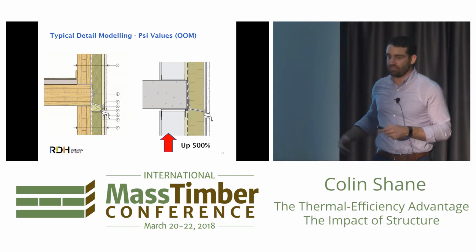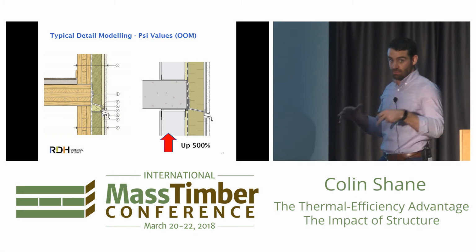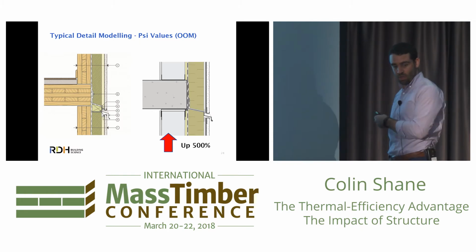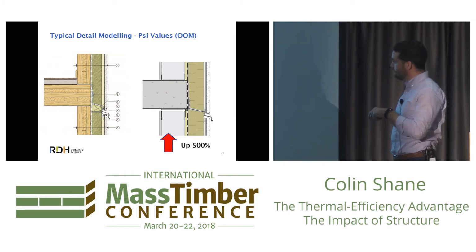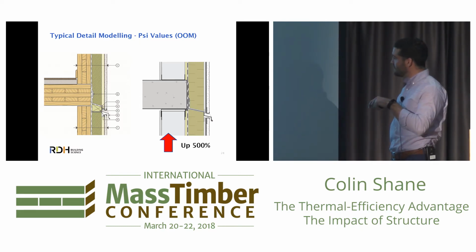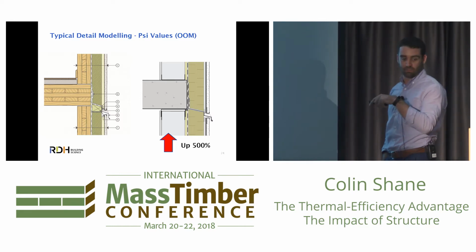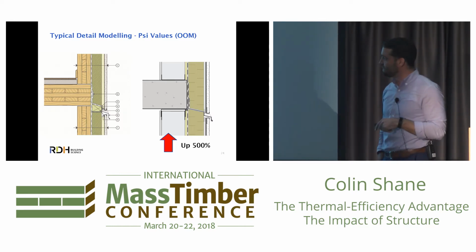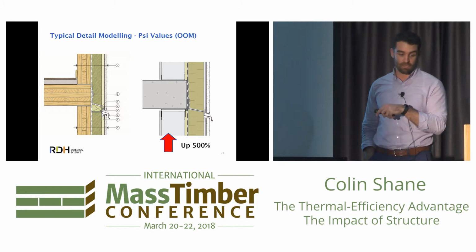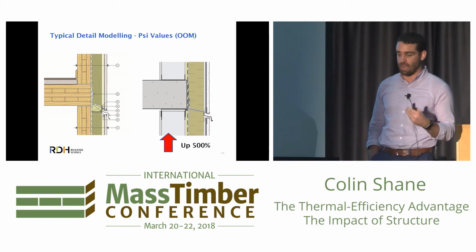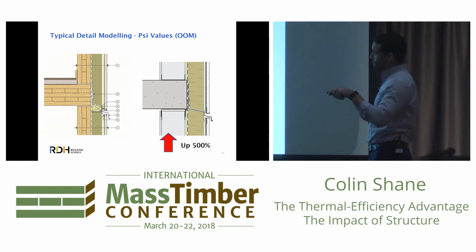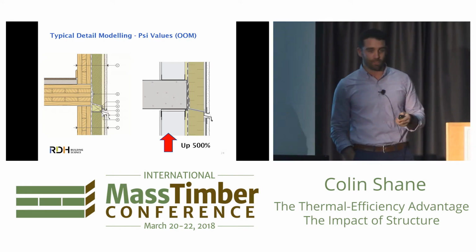Okay? Through-wall flashing details is kind of something we're pretty familiar with seeing, certainly in the Pacific Northwest. We maybe have a rain screen wall and we have a flashing at a floor line to divert water back to the exterior. So the reality of just putting this in, slicing through your insulation layer with a piece of sheet metal, interrupting that insulation and connecting that piece of sheet metal to really conductive heat, concrete and steel at these interfaces drastically jumps up the linear transmittance of those details. It's not zero with CLT, right? There's always going to be some thermal losses that happen at these details where our insulation is discontinued for a little bit. But huge significant differences just because of structural material choice. Okay?